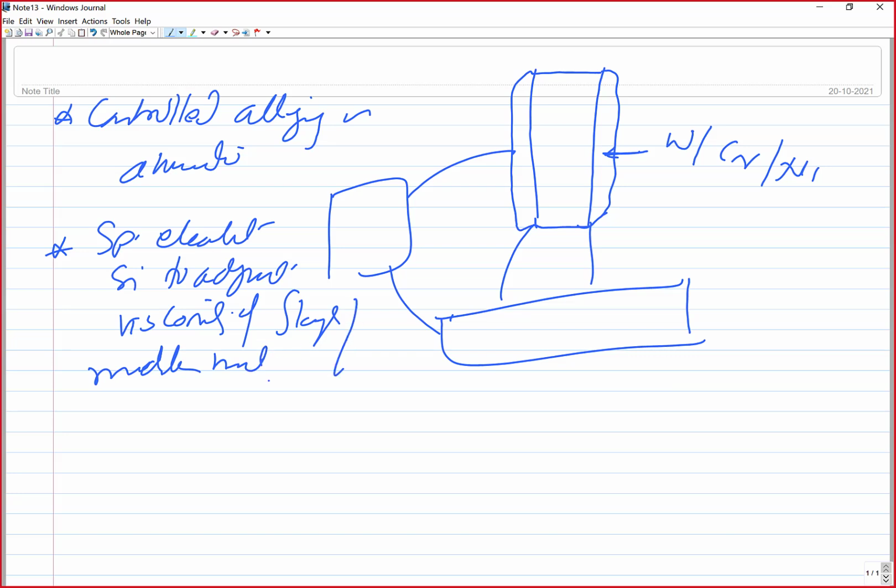This helps reduce the falling tendency of the weld metal when odd position welding is performed, either in vertical or overhead positions.